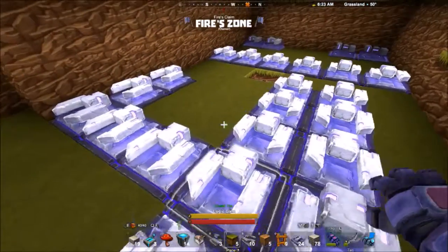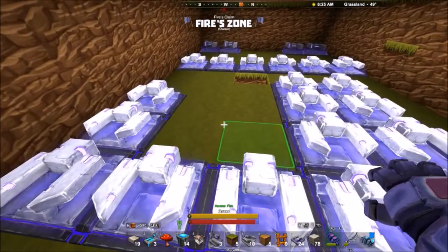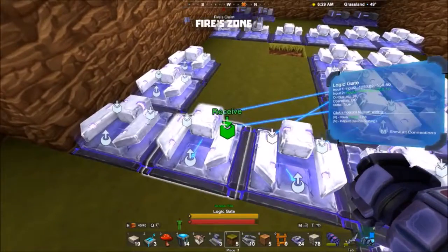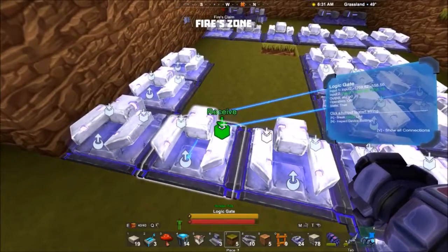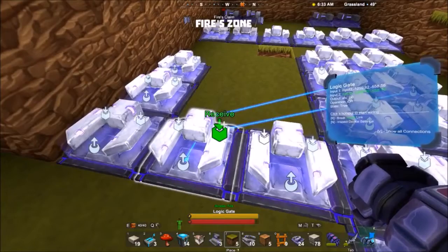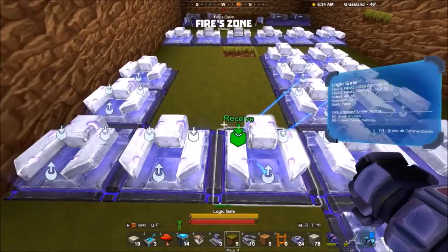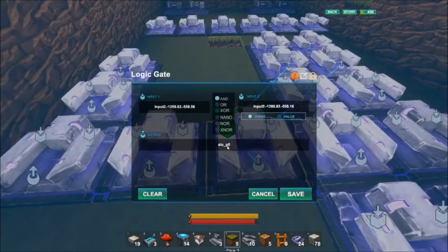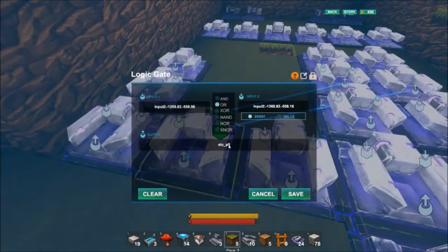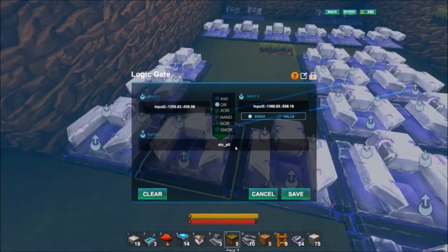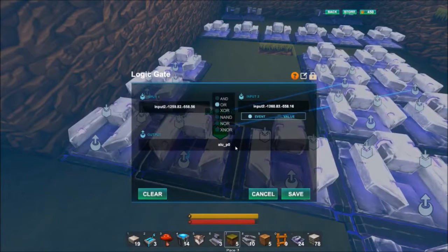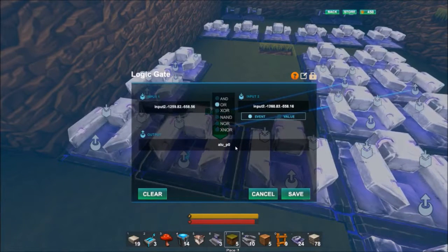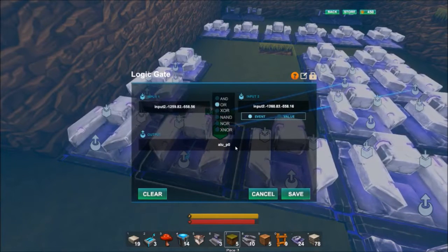The one that you have to change is the logic for the carry. On here we have two gates. One is going to be true when you have propagating, and the other one is going to be true when it's generating. I named them G0 for generate from 0 and P0 for propagate. So basically the propagate is going to be an OR. If you have a 1, it will mean that it will propagate the signal. If you have a 1 and you have a carry coming in,